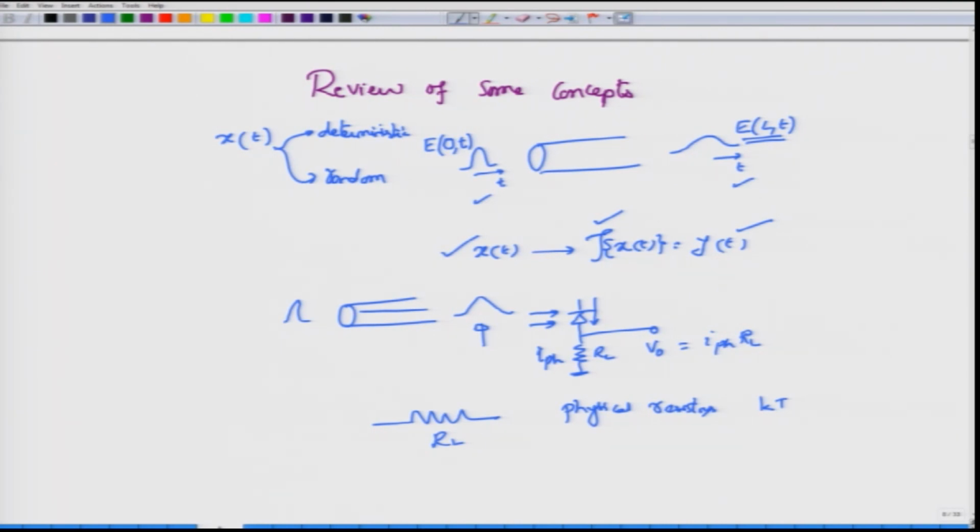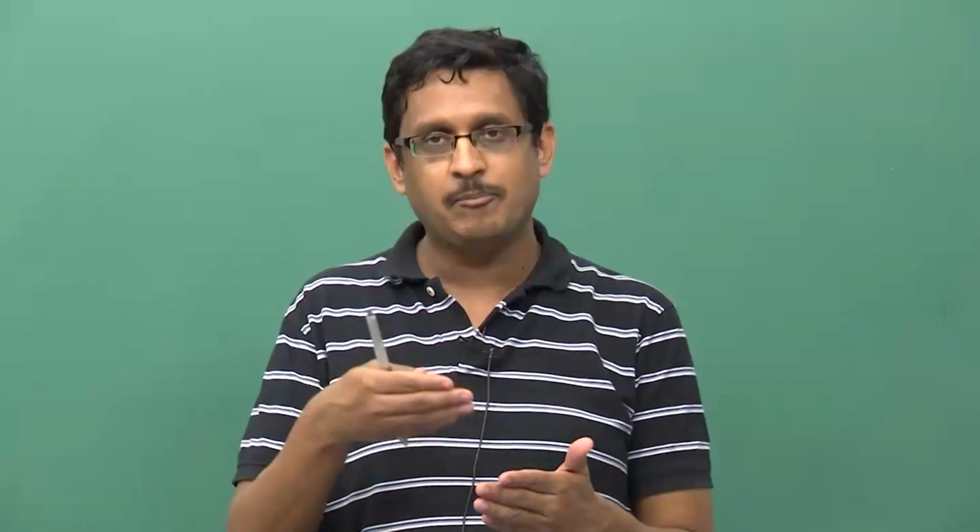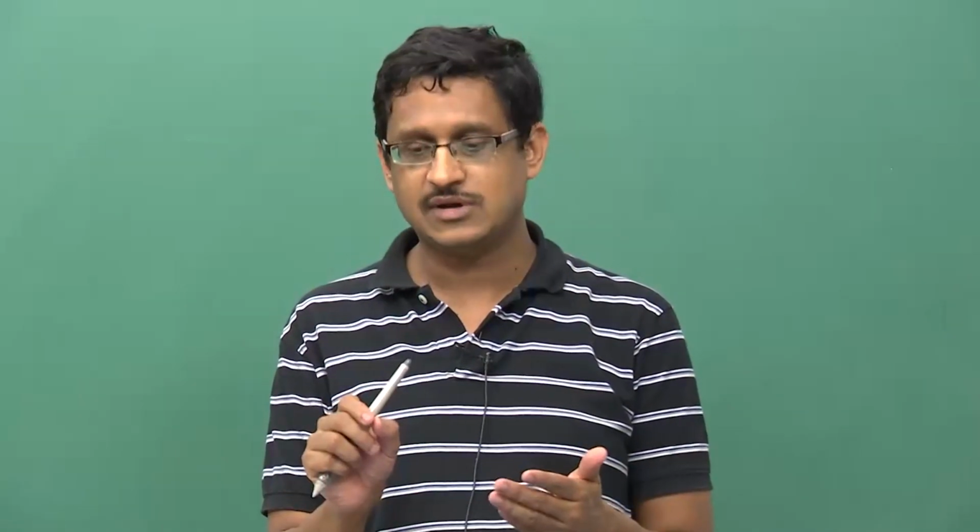Okay, I am just assuming that these are crystals, so therefore I am talking about band structure here, but it is not really necessary that way. So, the idea here is that if whatever material that you take has a temperature greater than 0, then there is an associated thermal energy which will then be imparted to the electrons, which will then allow these electrons to move.